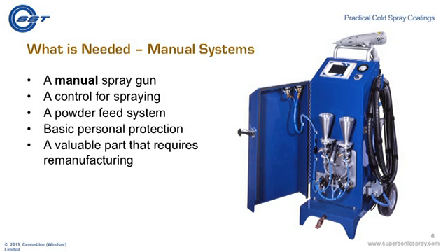I want to mention something here at this time that's quite important. A lot of the remanufacturing application requests that we come across have to do with a customer who maybe over-machined a certain component. In order to recover that component, especially where he's got quite a bit of value added into the part, he'll cold spray an excess of material, put it on the same CNC machine from which it was originally machined, and then machine it back to original specification.